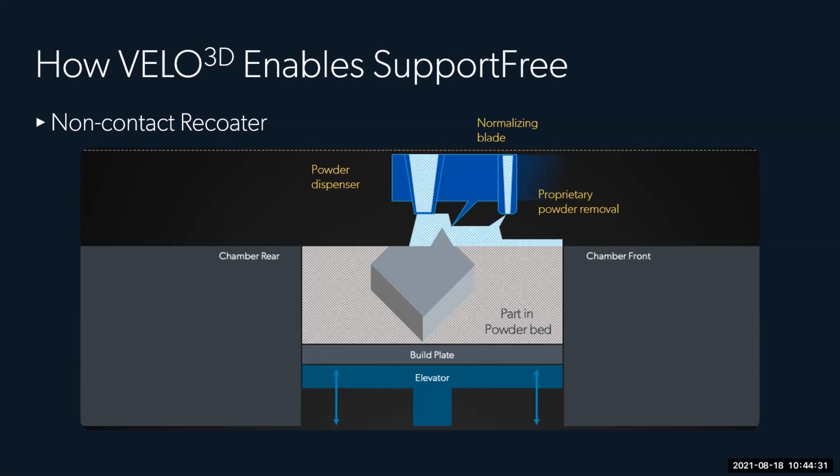In some situations, you may even have part material that's just barely sticking up above the powder bed, and naturally it might have solved itself. But as soon as you hit it with a metal blade, it's game over. Your print's crashed.